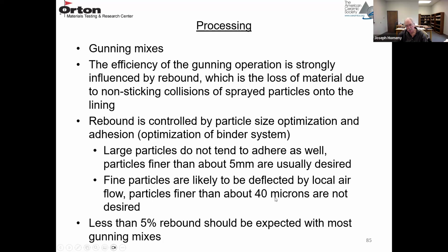So particles less than 40 microns are not desired. If the particles are too large, they'll bounce off the wall. If the particles are too fine, they may not reach the wall. If you can do an installation with less than 5% rebound, that's a pretty good job using a gunning mix.